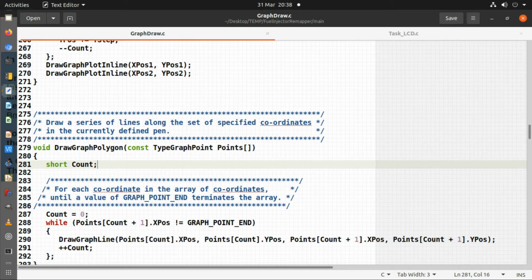What you should notice also is there's no calls to semaphores to lock the LCD display in these, because what these get called from is the application, and the place where the application calls these, it will be calling a series of these in a row, or it might be from a GUI control. It will be calling a series of these, and so the application itself at the outer bound will be locking the LCD display rather than having to lock it for every single individual one, and that makes things a lot more performant and also makes things simpler to understand.